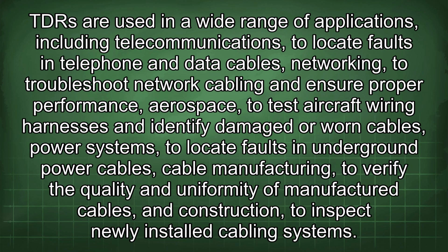TDR are used in a wide range of applications, including telecommunications, to locate faults in telephone and data cables, networking, to troubleshoot network cabling and ensure proper performance, aerospace, to test aircraft wiring harnesses and identify damaged or worn cables, power systems, to locate faults in underground power cables, cable manufacturing, to verify the quality and uniformity of manufactured cables, and construction, to inspect newly installed cabling systems.